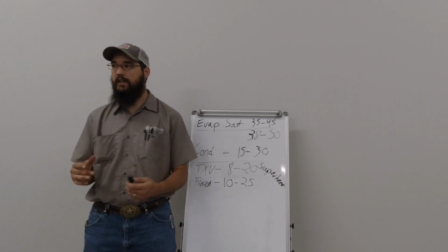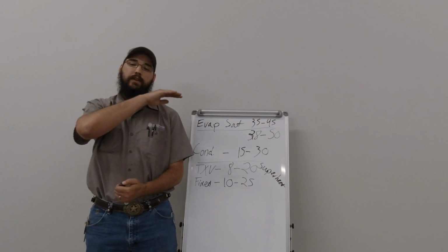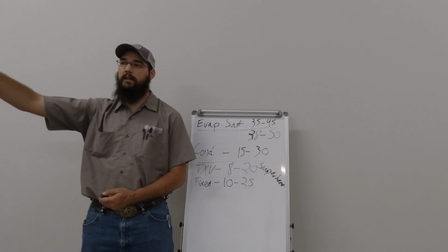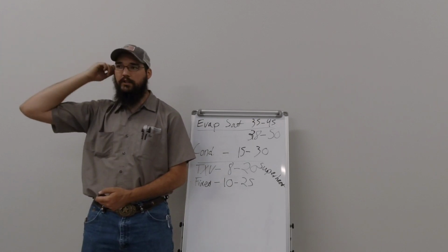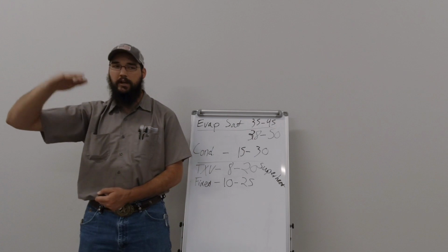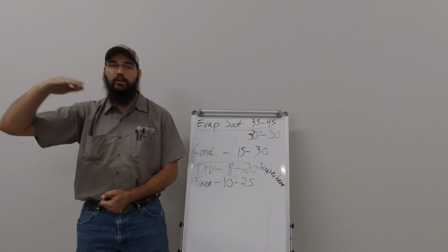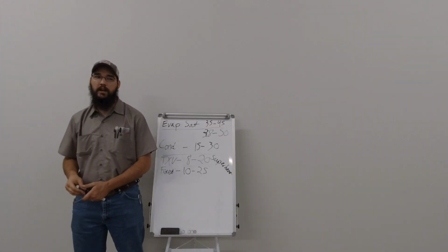And so every single time you make a single adjustment on that TXV, you've got to let that superheat curve flatten back out and that TXV balance. If you don't, and you're watching it constantly hunt to try to balance itself back out, and you then continue to try to still adjust it, you're going to be doing nothing but chasing your tail, and you'll never get it right.